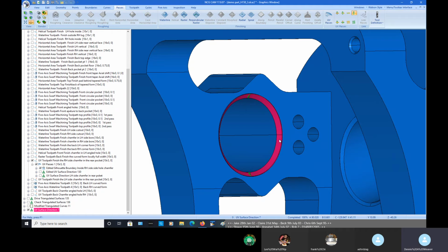In this case, it's just two surfaces. They happen to fall nicely so that everything is a common direction. Sometimes they're not in the right directions, but you can make modifications by swapping the cut and the order directions and reversing the UVs on the other two as well.